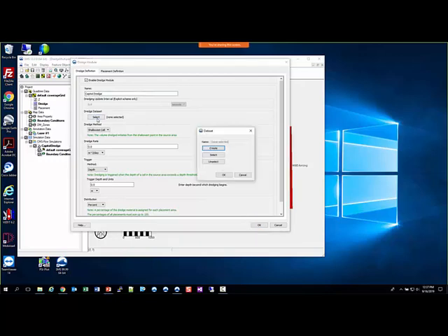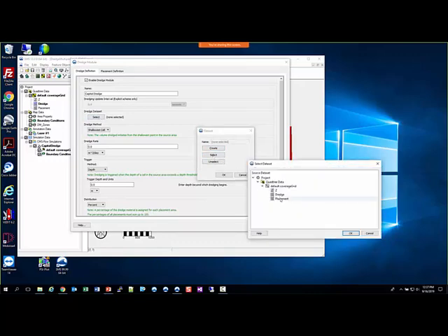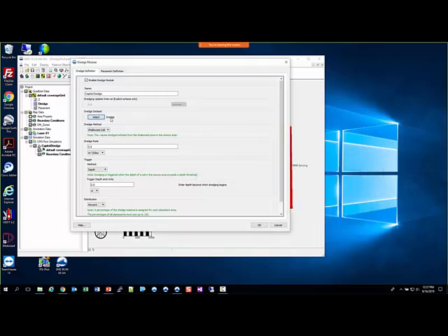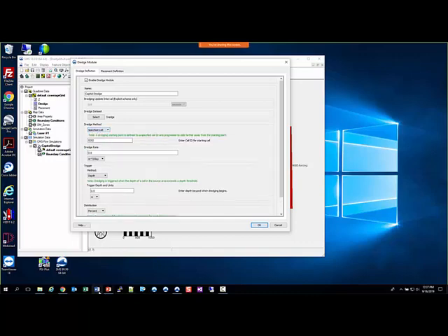We want to select the dredge data set, so we go in here, click select the dredge data set. If you see that, click OK, and we notice it populated this field here. We choose a dredge method, so it's either the shallowest cell or a specified cell, and so you could choose either one you wanted. In our case, we're doing specified cell. And let me go over here and make sure I'm putting in the right values here.